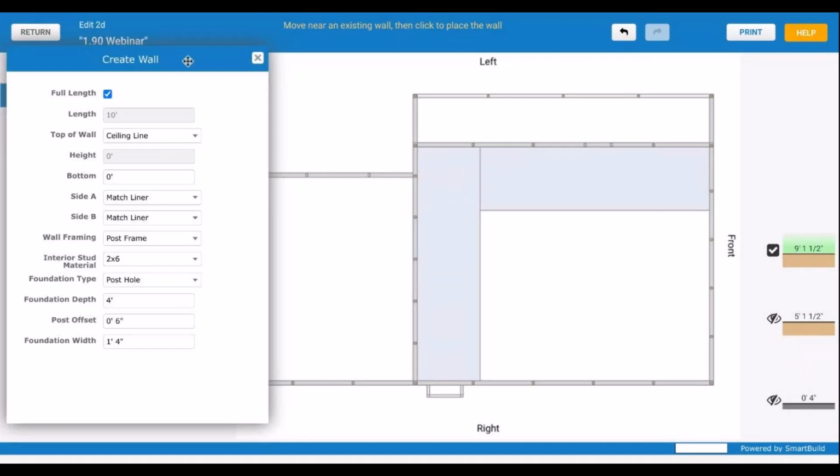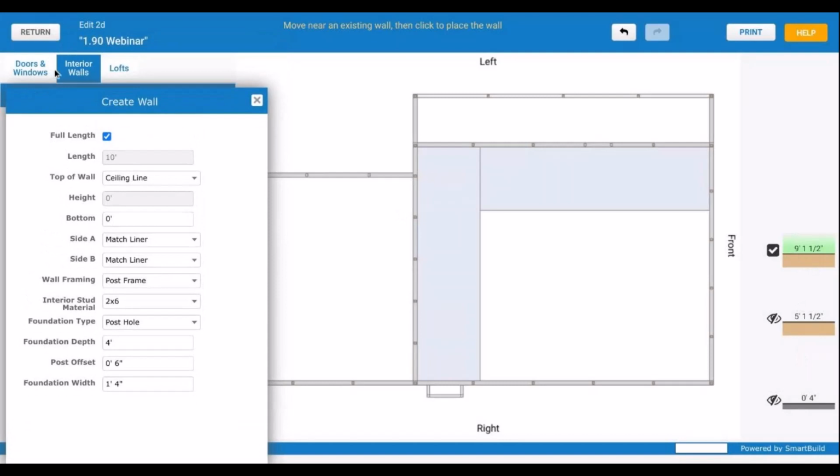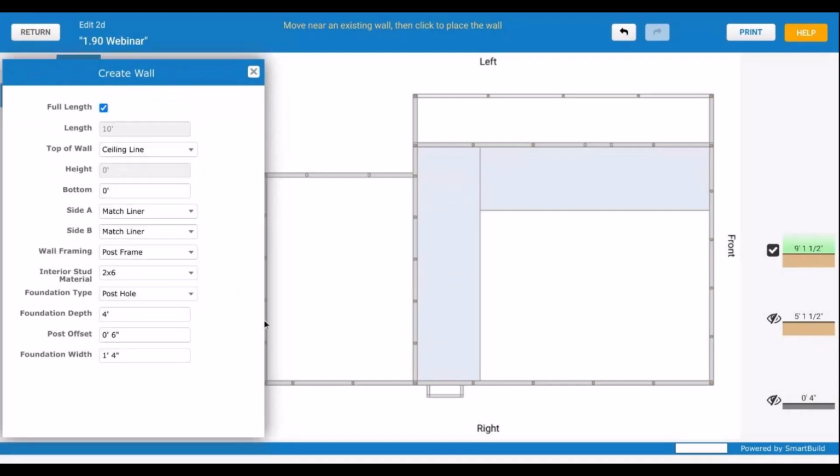Right now, everything we do with these walls, and if we put on some doors and windows, it's going to be relative to this active level. So something to keep in mind. And I guess while I'm thinking about this, if we put these walls or windows relative to this loft while it's active, and we delete these lofts, it's going to delete the walls and the windows associated with it. So just something to keep in mind, that these things get tied together depending on how you do this. But we can look at that in a little bit once we get a few things input here.